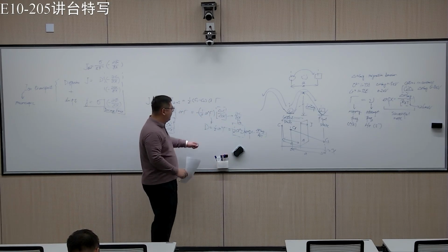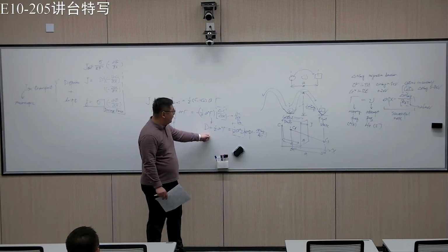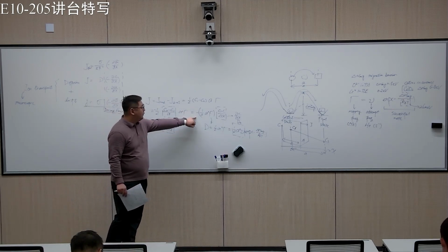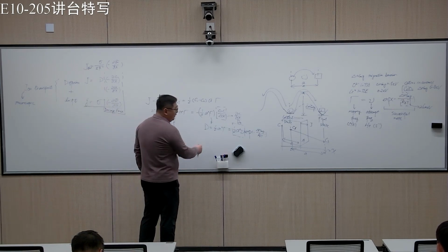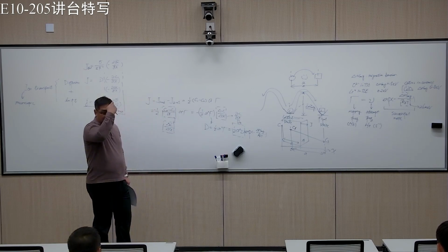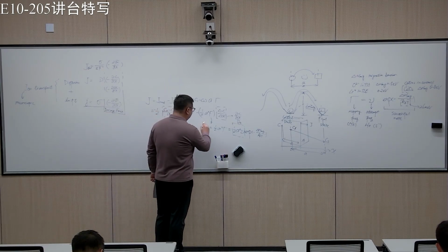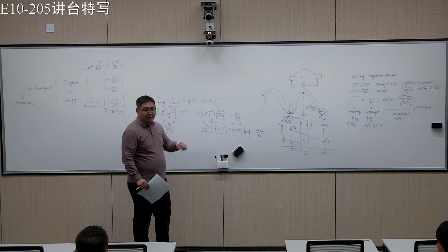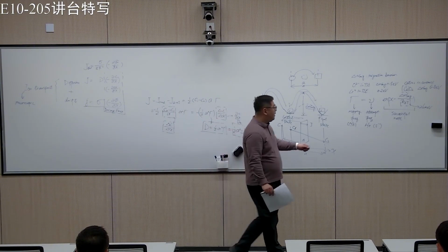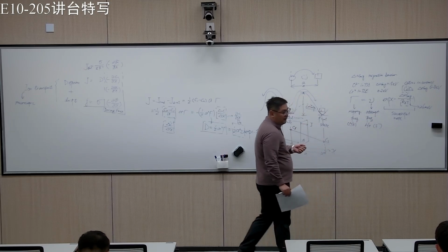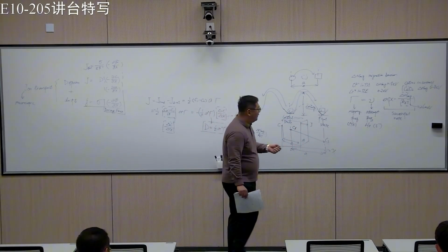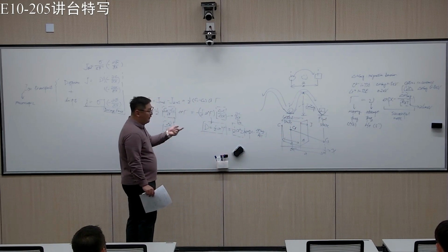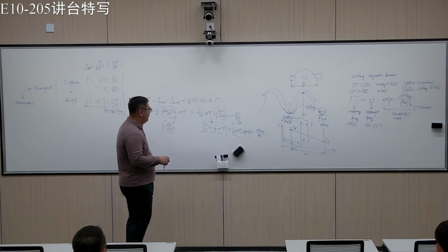As you can see here, you have the atomistic explanation of Fick's first law, and also the atomistic picture of the diffusivity. Diffusivity is related to two things. First is of course the hopping rate. This is kind of intuitive, because the higher the hopping frequency, the higher the successful hopping frequency, you should have the higher diffusivity.